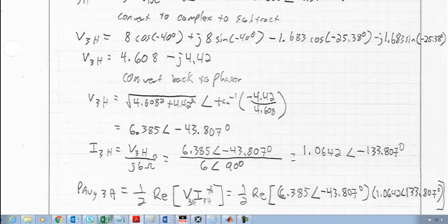So now I'm going to go ahead and convert this J6 into a phasor. And I can do that basically by inspection. If you think about it being on a real and imaginary axis, this is a positive value, but it's all imaginary, so that means it's all along the imaginary axis, which is going to be a phase offset of 90 degrees.